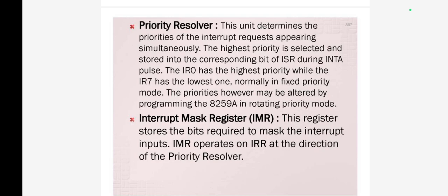Interrupt control logic manages the interrupt and interrupt acknowledge signals to be sent to the microprocessor for serving one of the 8 interrupt requests. This also accepts the interrupt acknowledge signal from the microprocessor that causes the 8259A to release the vector address onto the data bus.